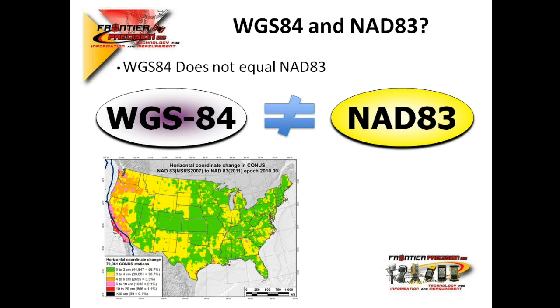One of the things when I first started training GPS, we really wanted to make sure everybody understood is that GPS has enough error in itself that it's important as a user to not induce more error into the GPS by doing some things improperly, whether it's selecting the wrong datum, or typing in a coordinate and you've chosen the 2011 datum, but the coordinate actually is a 96 adjusted value.